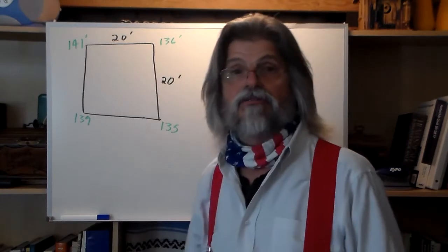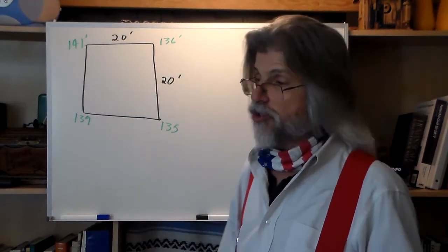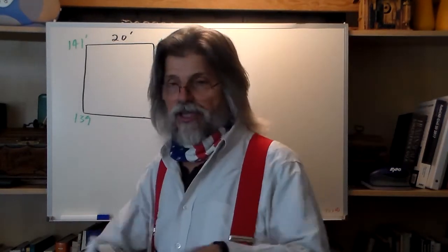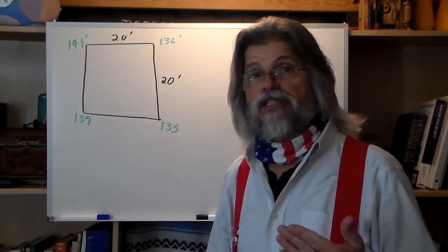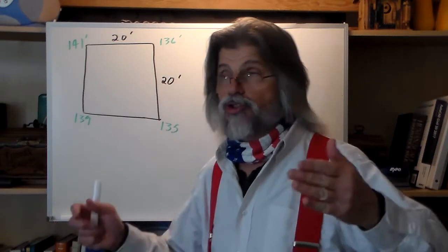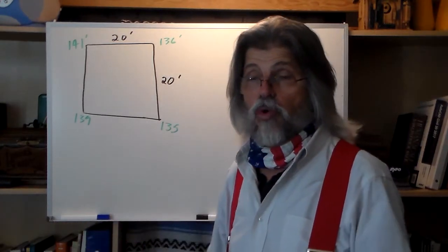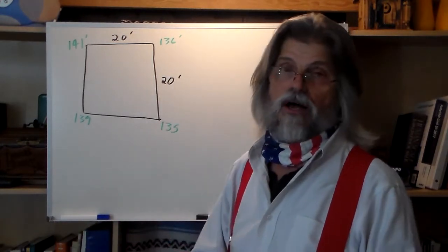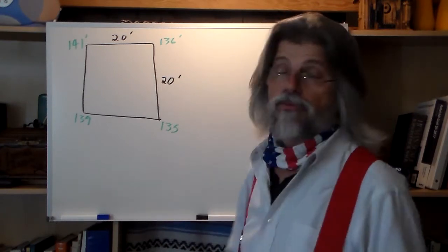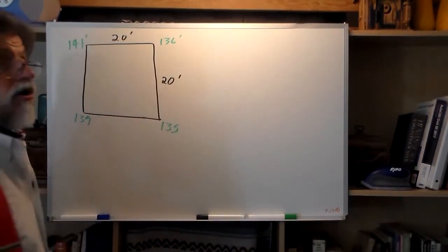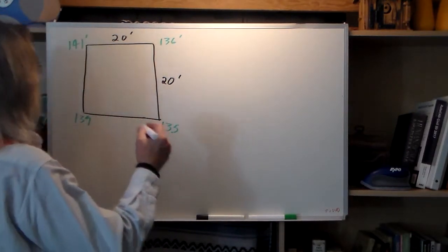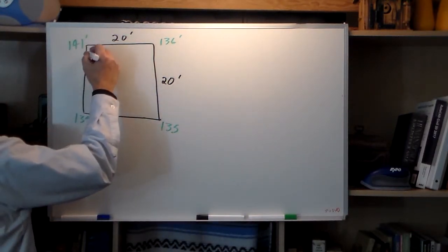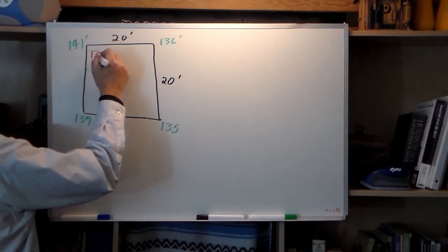You establish that elevation on those points initially, and you go back after they come in and pan out a bunch of dirt, and you reshoot the same elevations because you want to figure out just how much soil, whether it was rock, topsoil, what have you, was removed from this particular site. So you come back and you take the same shots in the same areas. And here you get 131.